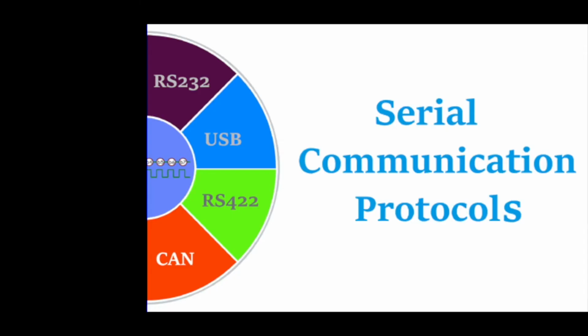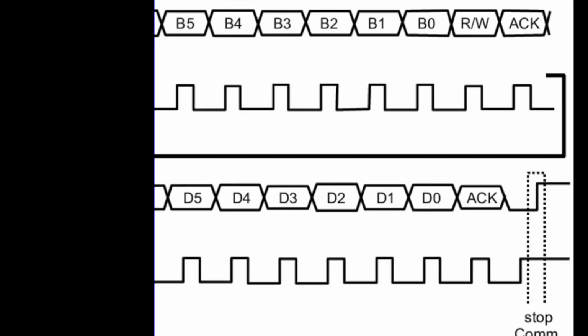So far, we've only been using one communication protocol to control our sensors. Going beyond simple one-pin sensors, I2C is a two-wire protocol for communicating with simple sensors and devices. You need 2 pins to control I2C, usually referred to as SCL and SDA.